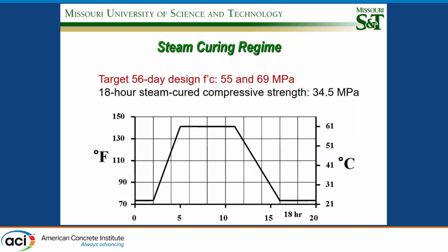We're covering different places in the country, and I remember one of the panelists, actually Dr. Schindler was one of the panelists, but one of the panelists from Seattle, from Washington DOT, was very adamant about having very high strengths for those precast pre-stress members. So 10,000 psi was the minimum.